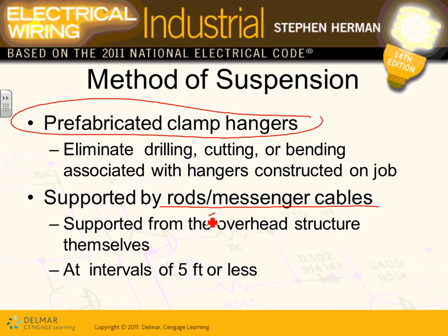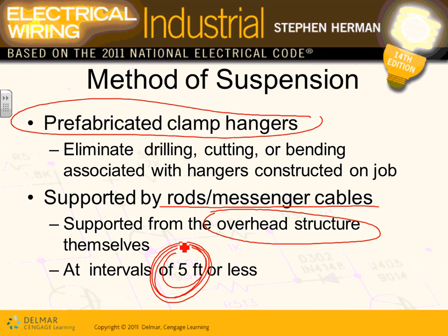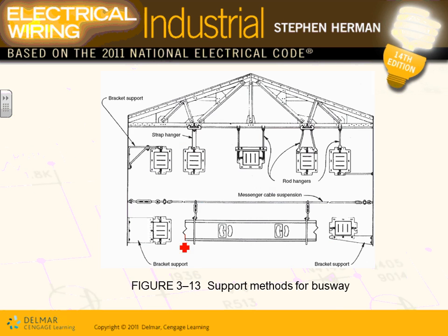You typically support it from the overall structure, which means you have to talk to your structural engineers. Typically these are steel buildings, guys, with trusses, and they have to be strong enough to hold all this weight. Remember, there's a physical mechanical weight of these busways. Did you guys see how they were all mounted through the structure? So you have to have integrity in your structure. They support them at typically intervals of what, Adam? Every 5 feet, they support them. You're going to look at the picture in a second.